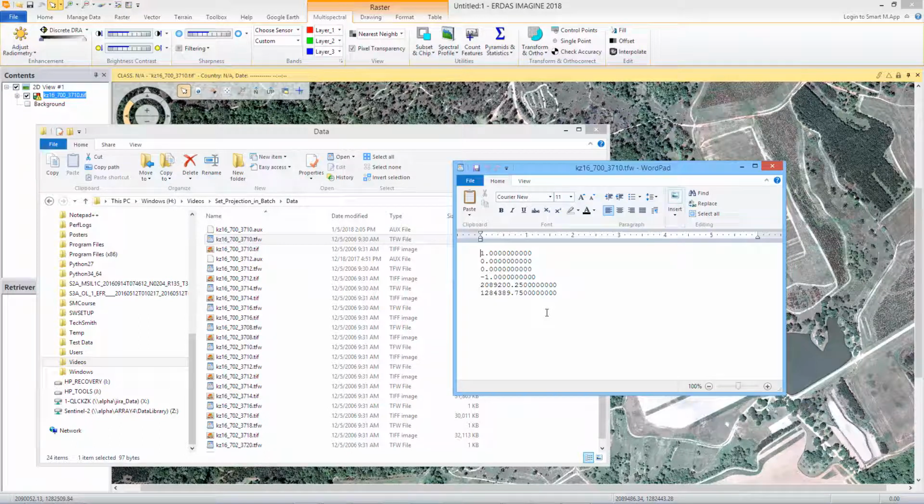It's generally not a problem if you have just one or two images of this nature. But if you've been provided with an entire air photo campaign's worth of ortho images, which could be hundreds if not thousands of images, you need a way to batch the process and make sure it happens correctly and doesn't corrupt any of your data. DASImagine actually provides tools to both edit the header of individual images as well as to batch the process across any number of images.